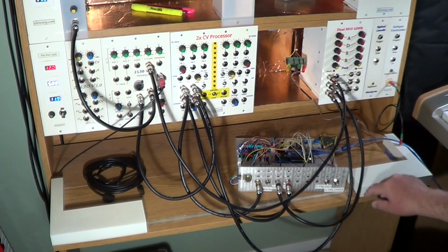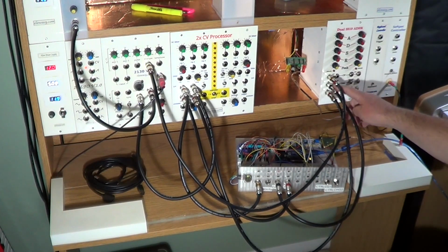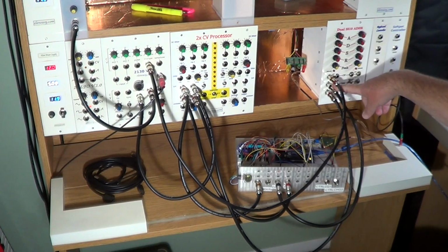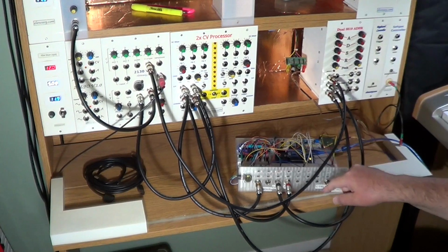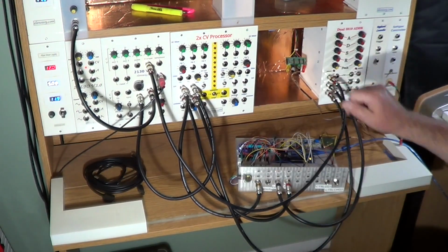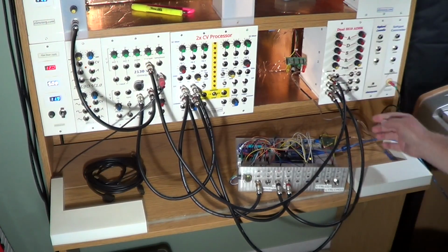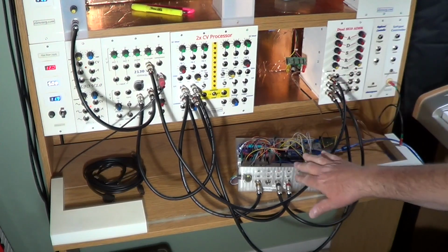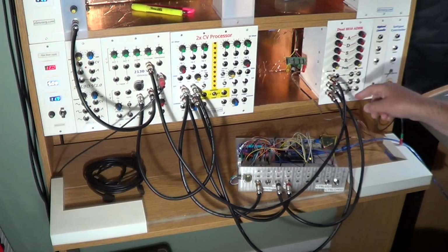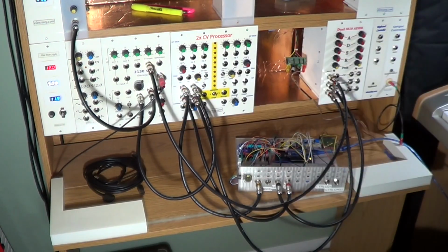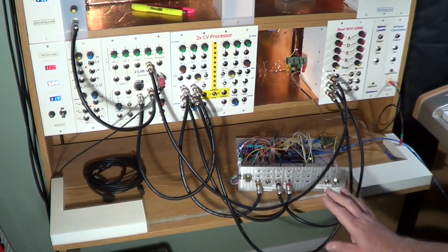This other cable sends the gate signal to the ADSR module, which will modify it to modulate the amplitude of the VCO output through its internal VCA. Since the ADSR module also needs the trigger signal, we take it from the trigger through jack socket on the sample and hold circuit. Summarizing, I have gate and trigger signals from the MIDI module going both to the ADSR module and to the sample and hold module. The output of the ADSR module goes to the amplitude control of the VCA embedded in the VCO.